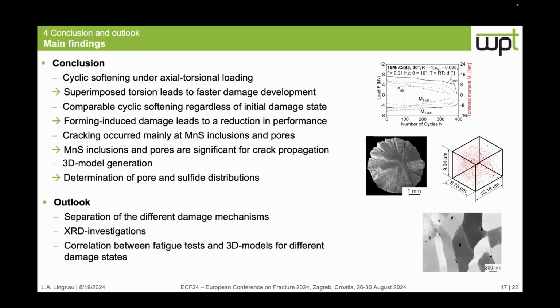At the end, I will give you a short outlook where we try to separate the damage mechanisms in the future, because it's a cold-formed component, so dislocation densities are very important for the fatigue lifetimes. And we try to get at that with XRD investigations, where we look at the full width at half maximum to get a quantitative idea about the dislocation density. At the end, we want to correlate the fatigue tests and the 3D models for different damage states, or different states in the fatigue life, like at 75% of the lifetime.